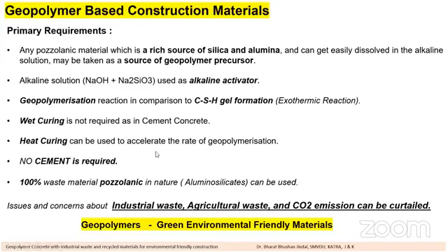A few years back, if you talk about maybe 15 to 20 years back, people were not able to digest this truth that without cement you can produce any concrete. But nowadays, I will later on show you a few case studies also, where you will be able to understand and believe that geopolymer concrete is much better than conventional concrete in terms of properties, in terms of cost, in terms of environmental effects. So 100% waste material, it may be 100% fly ash,